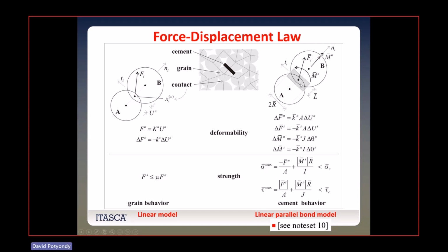In this sense, we put in what we'll call a parallel bond, and it's going to now basically have to update its carrying force in the cement, and it's carrying a moment in the cement, and these are the equations it's using. This is relative normal and shear motion in the cement. This is relative rotations. It's going to have to know what the cross-sectional shape of this is so it can compute the moment of inertia, and it can compute the polar moment of inertia, because for these spheres, it'll also resist twist. Okay. And then this is how we compute the outer.